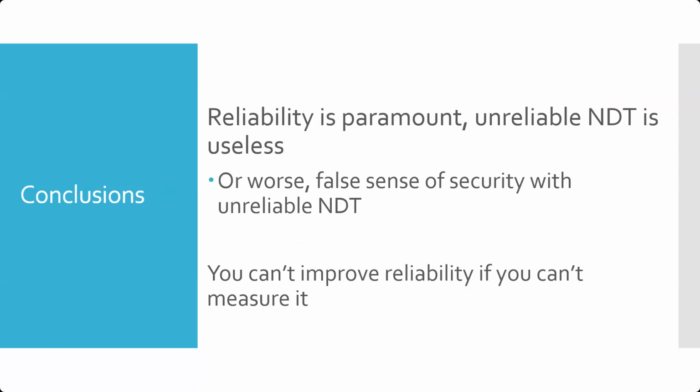So the conclusions that come from this: the big one is that reliability is paramount and unreliable NDT is useless, mainly because if it's unreliable, it doesn't tell us anything, or an even worse case is that it's hiding things. If things are being judged airworthy or serviceable when they're not, that can lead to a false sense of security and ultimately accidents or failures in service.